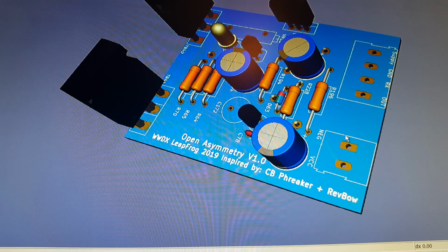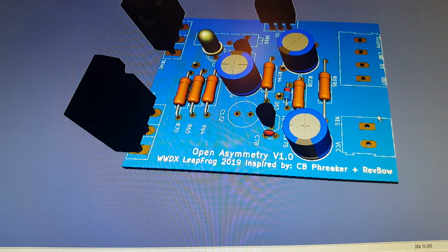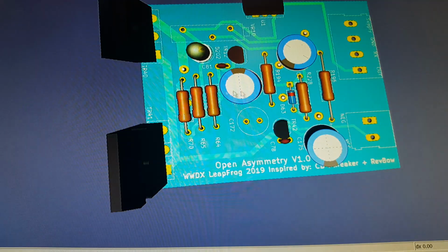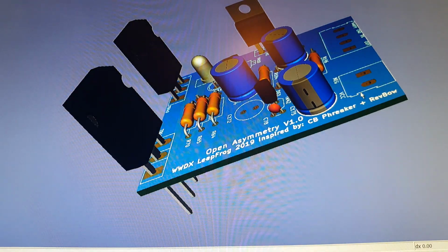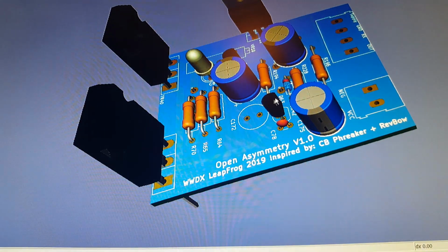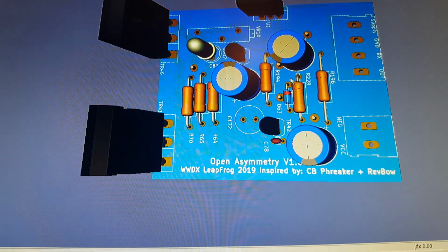But the issue with bypassing the preamp going directly to the high-level audio IC is that in transmit you'll actually have your audio come out through the speaker. Like a talkback, which is not what we want. That's when you have an external audio input source going to the board and you do not have it keyed up and you're going directly to the high-level audio IC. You'll get your audio source going through your speaker.